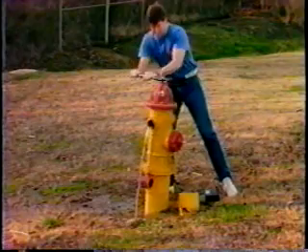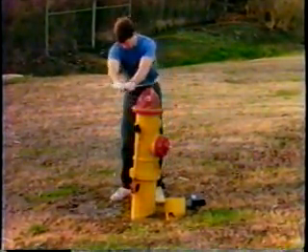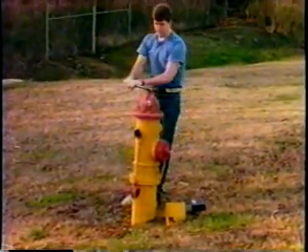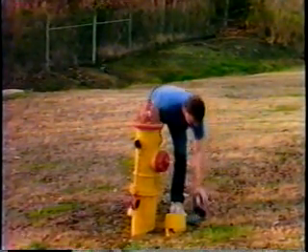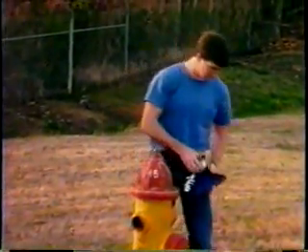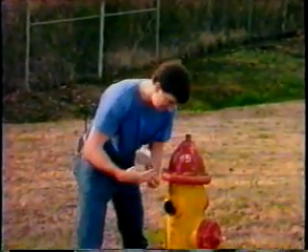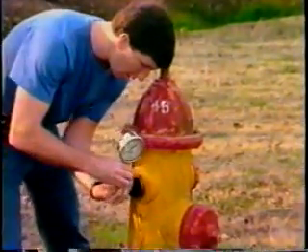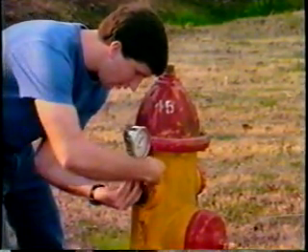This is done to prevent any debris from flying out of the hydrant outlet and hitting the gauge and damaging it. It's amazing some of the things that children and vandals will put inside of a hydrant. Once he has flushed out the hydrant barrel, it's time to bring out the pitot gauge. In this case, he's going to be using the clamp-on gauge. It's important to clamp it on tight and as close to the center of the hydrant outlet as possible.